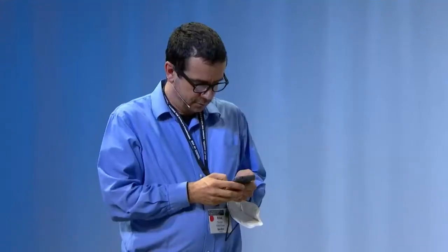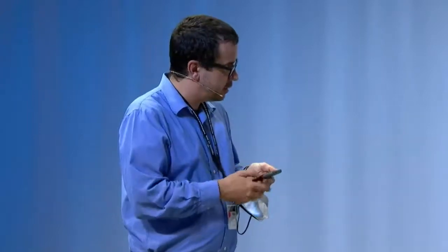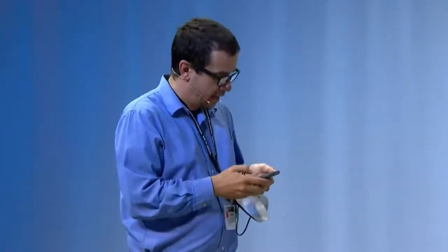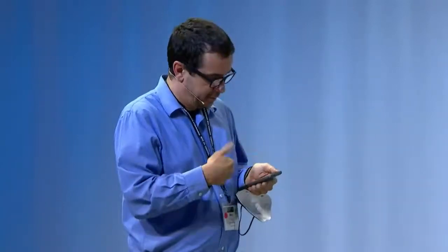Okay, thank you. We have one question from Christoph Gollop, and my phone is behaving weirdly here. When we put a 1 gigabit link onto a predominantly 100 megabit IVN, wouldn't there be a risk of actually losing packets in the gateway to the vehicle because we're overloading it, if we do not coordinate the flash sequence correctly? I'm paraphrasing because it's always scrolling away, so I can't read it off really.